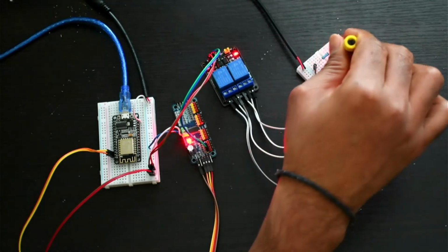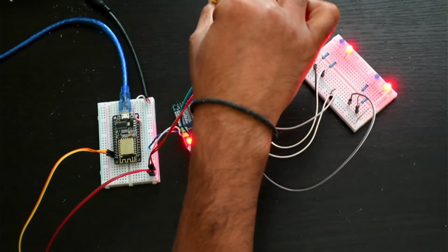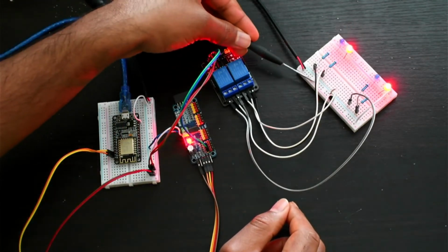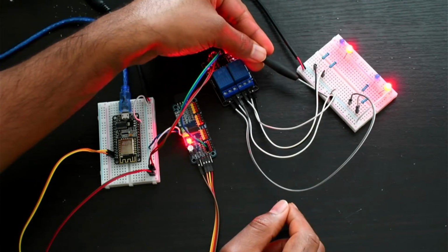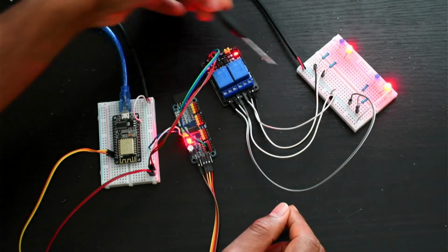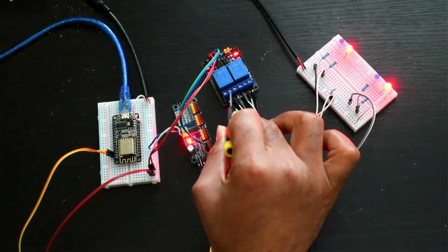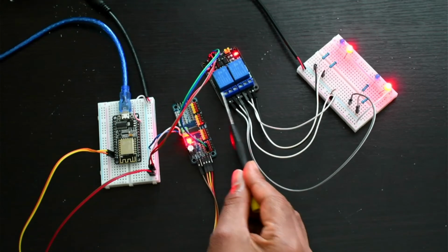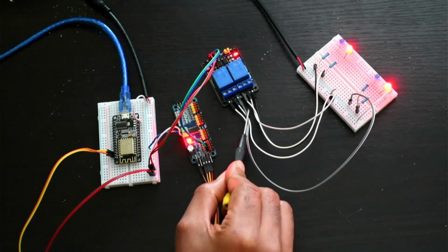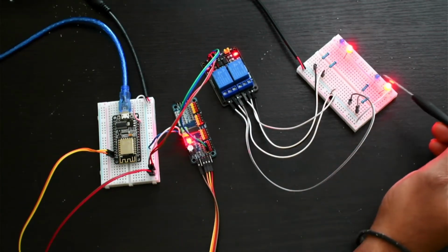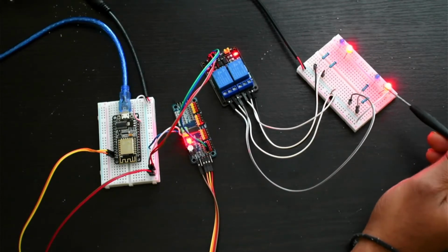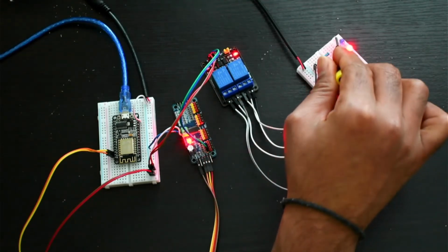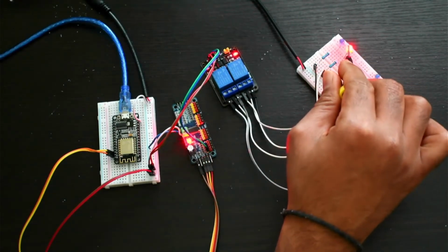Now let's come to this side. Here we can see this is an external 12-volt power supply which is coming from the adapter. It's going to this breadboard. From this plus 12-volt positive side, I have taken it to the common, which is the middle pin in both the relay switches. And from both the sides, you can see gray and white going here. Gray is taking power for the blue and white is taking for the red. Here black and white are taking power from this relay switch, and black is powering up the blue one and white is powering up the red one.